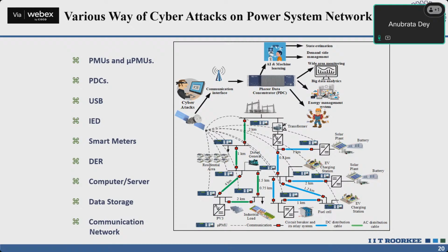Now whenever PMU sends the data, it sends the data through some routers or network switches. So an attacker can easily attack this pilot wire or communication medium, either wired or maybe wireless. Usually when long distances are there, the data are transferred through optical fiber cables. And if it is small distances, let's say within 5-10 kilometers, then it is sent through Wi-Fi network. It depends.